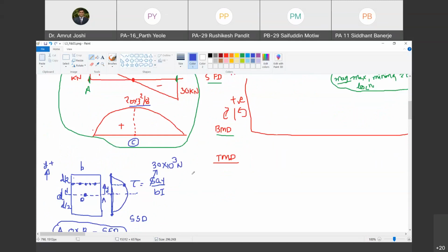Yes, sir. What is A? So if I am drawing the level at Y and neutral axis falls on this side, the remaining area opposite to neutral axis is A. Are you with me? Yes, sir. So wherever I am calculating, when I am at Y equal to plus D by 2, at that time A is 0 because there is no area remaining.